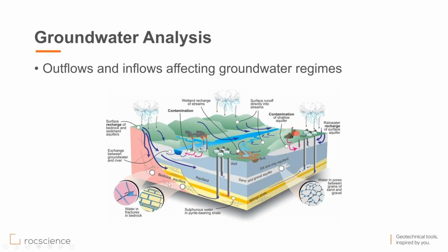If you have aquifers in the bedrock, this is the pore water in the bedrock between the joints and features of the rock mass. And you have pore water in the sand layers. Looking at all these scenarios, we can simulate them in our programs. There are formulations and methods for that, and the effect of this pore water pressure can be included in slope stability calculations in Slide2.